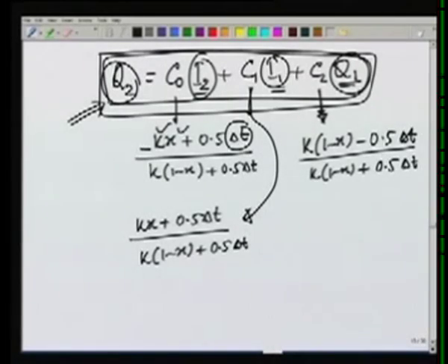So in today's lecture we have seen flood routing. There are different methods of routing the flow, either through a storage reservoir or through a channel. The storage reservoir routing is also called level pool routing because we assume that the reservoir level is horizontal and we don't account for water level variation inside the reservoir.